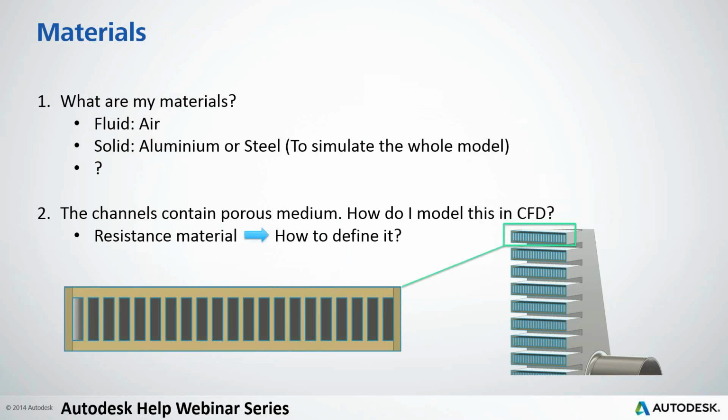So, to explain the picture: the fins have a simple geometry, so we can calculate the area of one opening, multiply it by 21, the number of openings, and then calculate the free area ratio. So, the next slide.